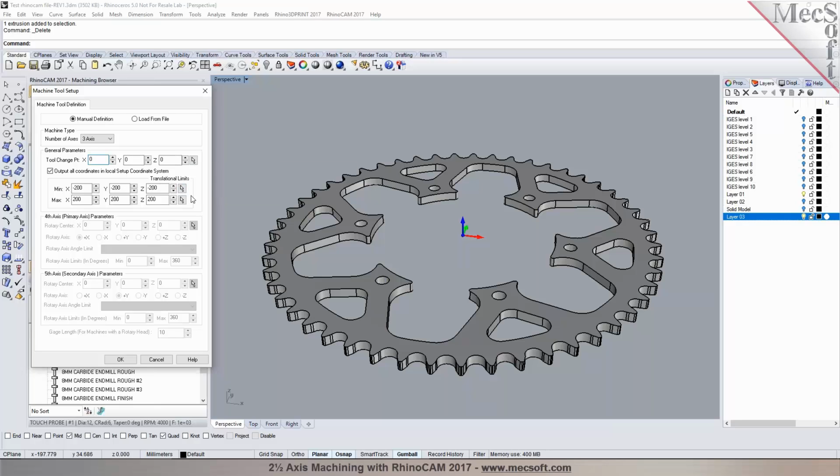If you are working off a manual tool change and you'd like the tool to be moved to a specific XYZ origin location, based off your origin location, you can specify the coordinate value, and in the post we can set it to output this information as well.